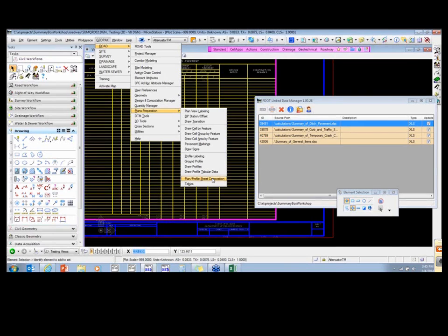I can't go to my design file, say I'm in signing and pavement markings, where all my pavement markings are in my design file, and create all my calculations there. It doesn't work that way if you want to use this option. Once I've done that, I can bring it out by sheet.